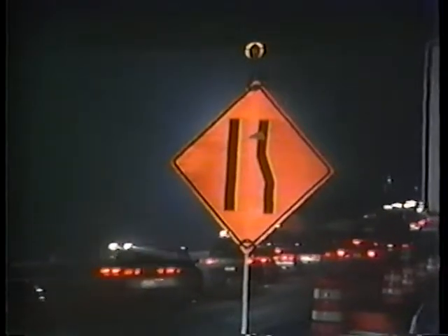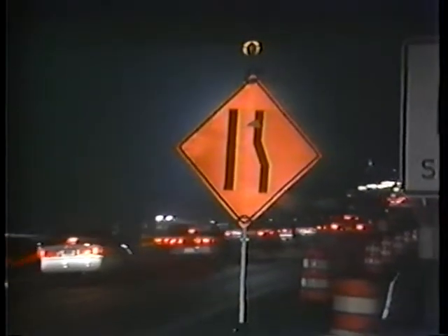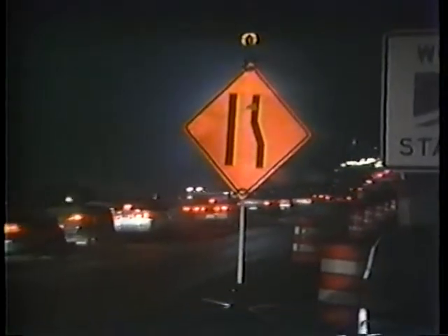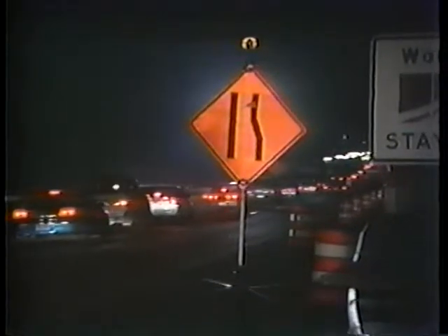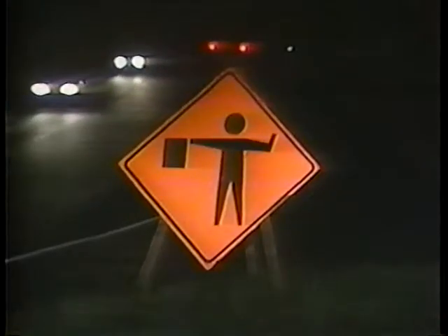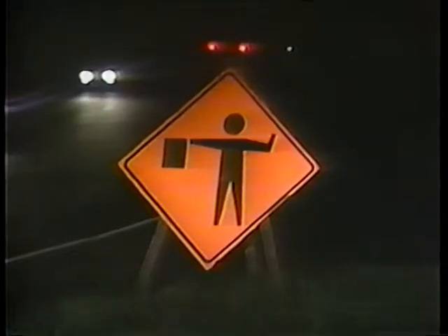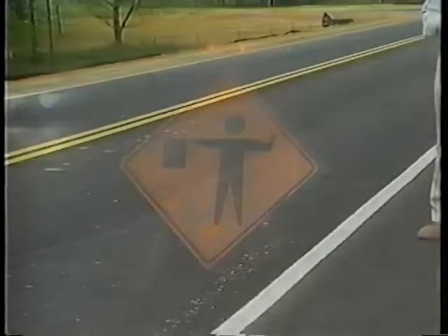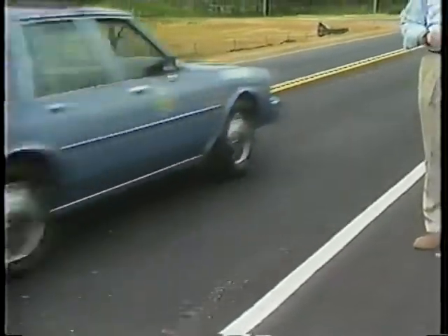All signs used at night are required by the Manual on Uniform Traffic Control Devices to be retroreflective or externally illuminated. Lighting from existing streetlights does not meet this requirement. Pavement markings are very important in guiding traffic through work zones. Pavement markings, delineators, and channelizing devices outline the traffic path around a work area. Drivers use pavement markings as a primary means of guidance.